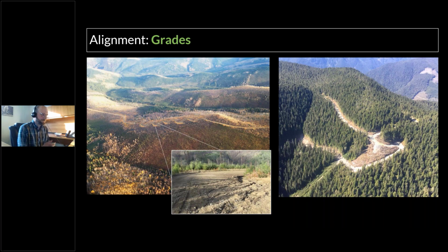The switchbacks are stacked right on top of each other, and you can't tell from that aerial view, but they're actually dished. So the big takeaway in our first webinar wasn't to not dump water off switchbacks. It's to try to preserve those natural flows.